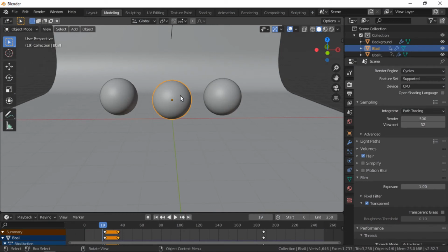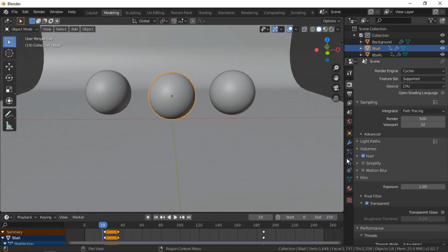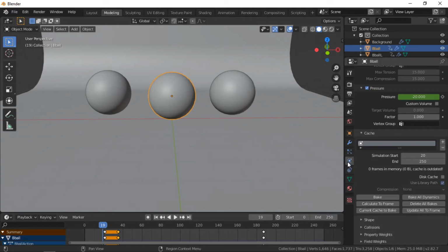This animation uses physics within the animation. It is recommended to bake the physics animation before rendering. Baking essentially saves the animation. This allows the render to run more smoothly and less likely to have any glitches. A bake can be cleared and rebaked if changes are needed to the animation.